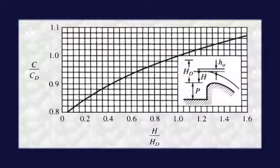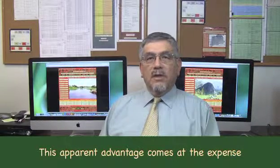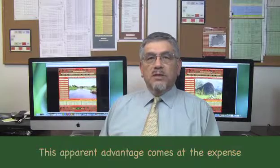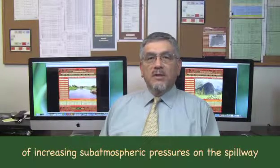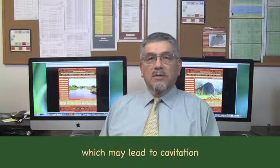As shown here, the discharge coefficient increases with the operating head. Therefore, a spillway crest becomes more efficient at heads that exceed the design head. However, this apparent advantage comes at the expense of increasing subatmospheric pressures on the spillway, which may lead to cavitation. As an example, assume the following spillway data.